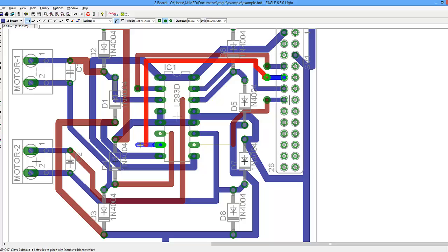Okay, here, and then yeah, place it here. And you tell me, you'll put this X here telling me there is no via. So simple, I'll go here and add my own via. Just make sure that the dimension of the hole is 0.8 mm, and then enter, and then place it.